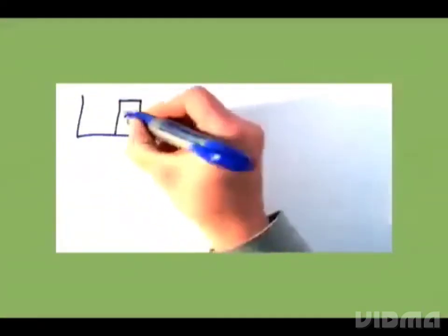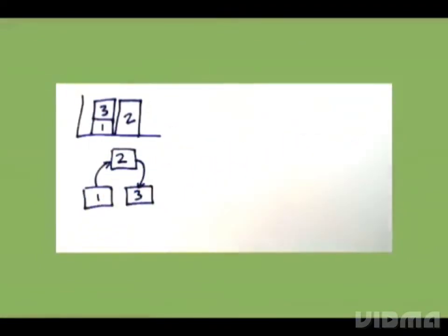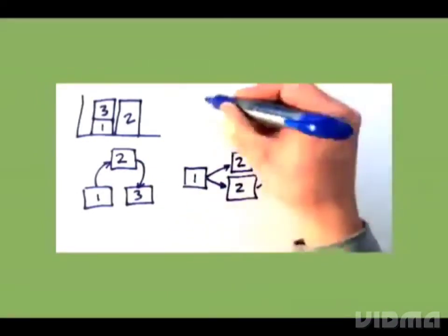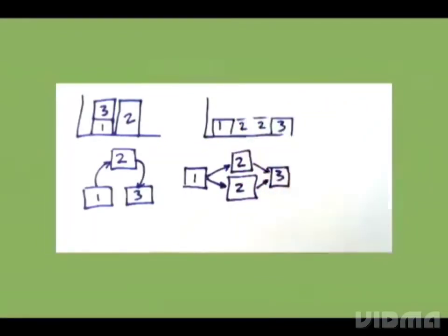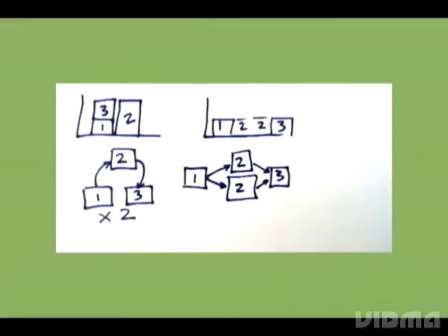Remember the improvement options we had? In the first option, we could combine the first and last step and end up with a 13-second cycle time. In the second option, we could add a second cutter and end up with a 6.5-second cycle time. Another option could be to combine the first and last step and run 2 cells to still end up with a 6.5-second cycle time. Another option would be to run 2 shifts of the combined cell, increasing the available work time. The cost of equipment and the space it requires might dictate which of the options we select, but running 2 cells would give us more staffing flexibility. So let's select that option.